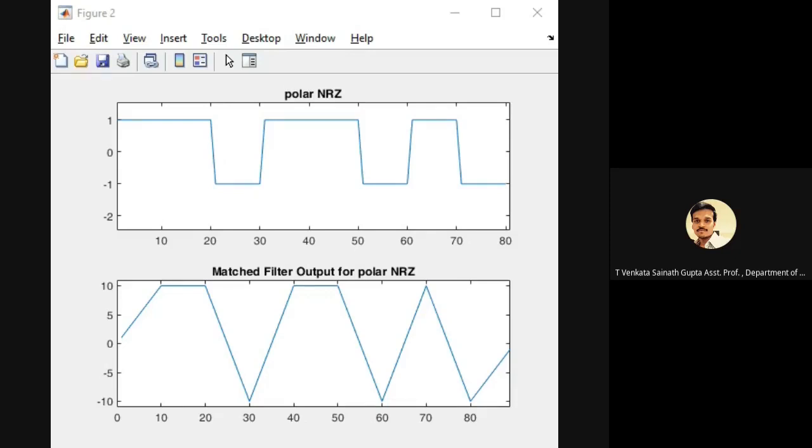We are not talking about the Fourier transform or frequency domain representation. C9, whatever you had written, that is the frequency domain representation of a rectangular pulse. So if you represent your rectangular pulse in the frequency domain, you get a sinc function. Or if you take a sinc function and represent it in the frequency domain, you will get a rectangle. Fine, you understood the point. So whenever you do a convolution between two rectangular pulses, you will get a triangle.